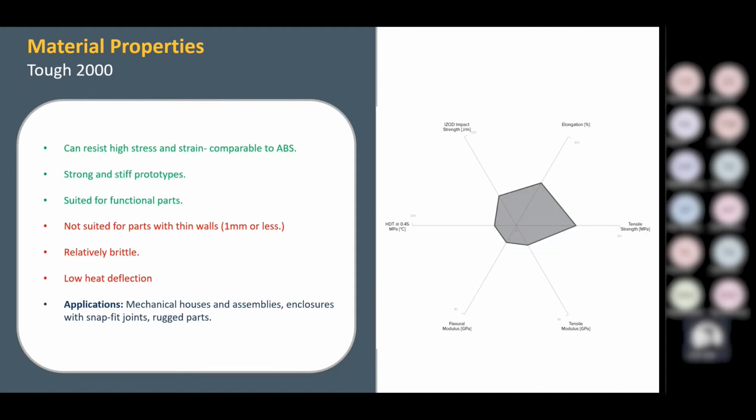Good point, actually. So one thing with this as well, with SLA, the components will look really highly detailed, but we would recommend against printing less than 1mm in terms of thickness, at least for the main wall details. So anything structural needs to be at least 1mm thick. You can still do tiny surface details, like down to 3 microns attached to it, if you're going to see it. But don't just try printing something that's, say, 0.5 millimeter.